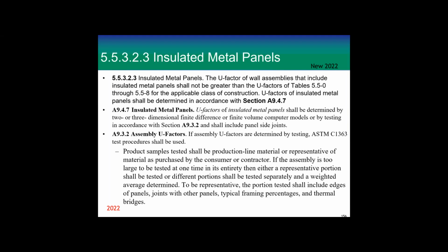The architects will say we're using them, and I call the architect and say, okay, tell me what the U value of the metal panel is, and they'll say it's got an R of 30, and I'll say an assembly can't have an R of anything. I need to know what the U value is. And they'll say the manufacturer tells me it's R 30, that's all I got. It happens all the time to me, because it really bugs me that they're trying to sell.